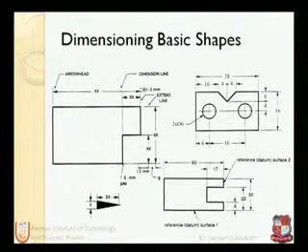On the next, there are some figures. First of all, we need to understand the arrowhead. As we saw before, this arrowhead has a great application. The arrowhead length is 3 times the height. For example, if the height is 1 mm, the length of the arrow will be 3 times, that means 3 mm. The arrow cannot be bigger than 5 to 6 mm. Usually it's drawn with a height of 2, and the arrow is maximum 5 mm.